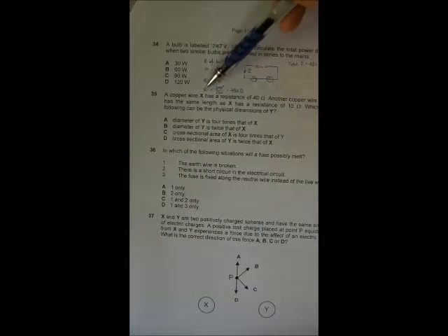So the first step is to use your P equals V squared over R, and find out what is the resistance for the bulb. And then you know that the bulb is connected in series, so then you can work out your total resistance is 960. Now down here, you need to assume that the power supply is 240, but if not, you may have too many unknowns.